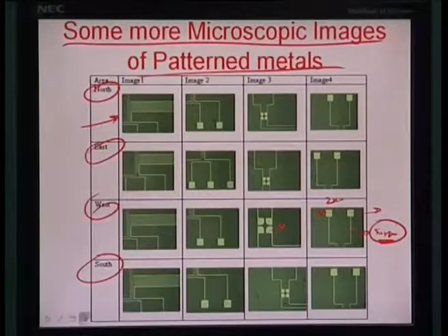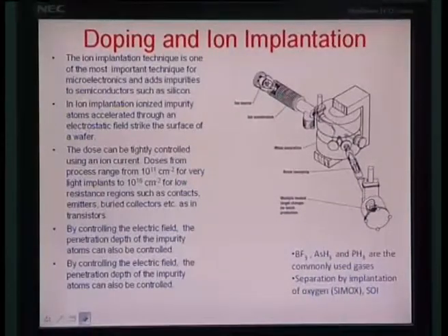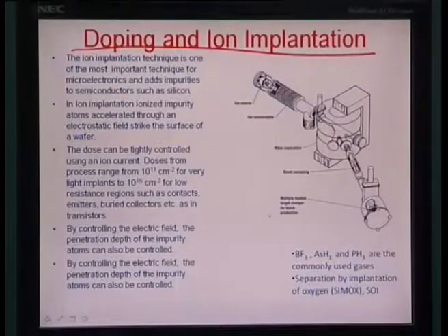features onto the surface. Let us talk about another new area which is related to how you can introduce defects which can be group 3 or group 4 inside silicon material. So this is also known as doping and ion implantation, and why is it needed is because, as you know, the semiconductor can be P or N type based on whether you have an excess, whether the dopant belongs to group 5 and you have an excess electron that it can share with silicon apart from its regular 4, and if it is group 3 you have an